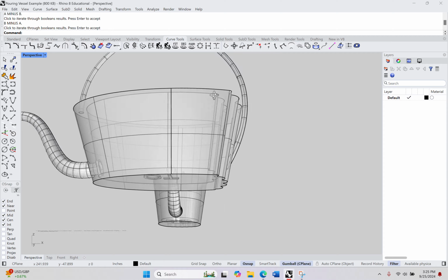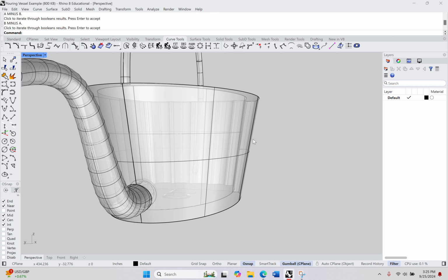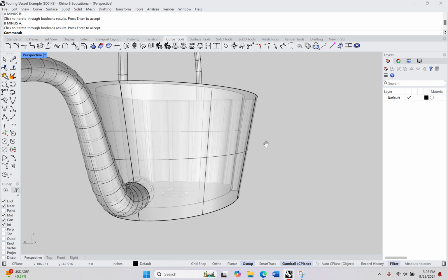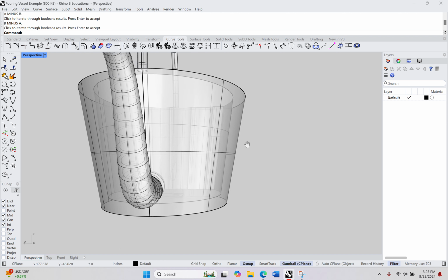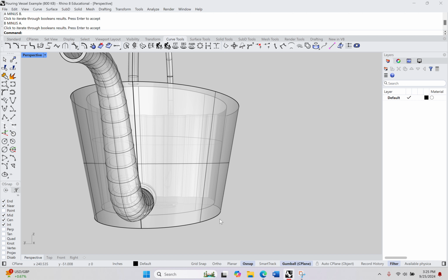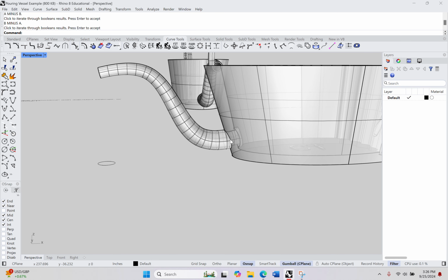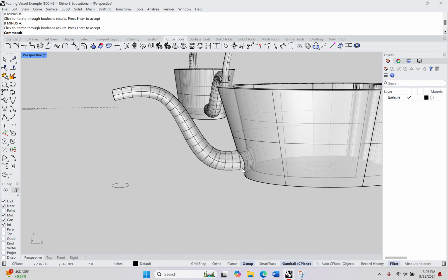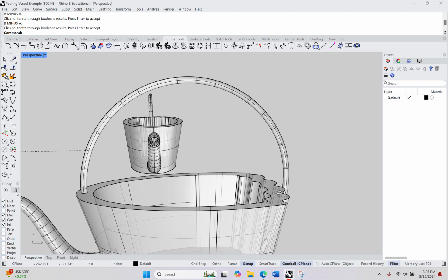Now, if you want to Boolean, if you want to press shapes into exterior things, remember when you slice your STL files in Ultimaker Cura, there's the whole concern of support structures. So more than likely, you're going to want to have supports underneath like the spout. You might even want supports underneath this, although not necessarily.